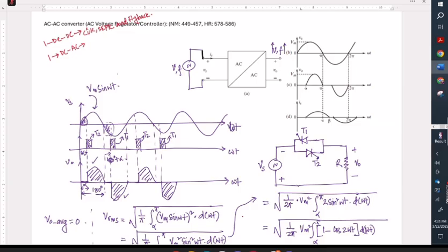So for the inverter, we discussed half bridge, full bridge, 180-degree conduction, 120-degree conduction, sine PWM, and applications of the inverter, like induction heating. So based on that theory, for each and every inverter, you have to know the output waveform Fourier analysis, and questions will be given based on that.